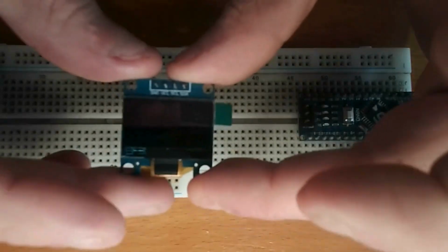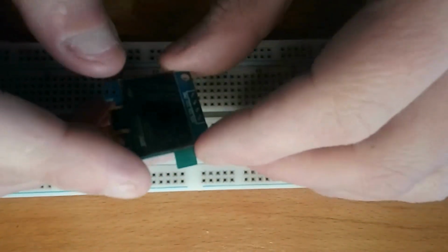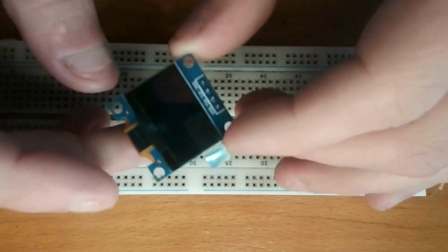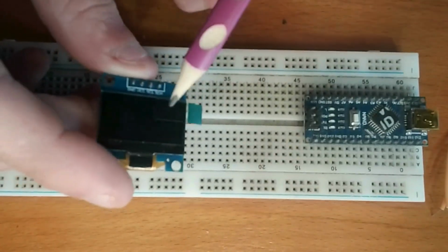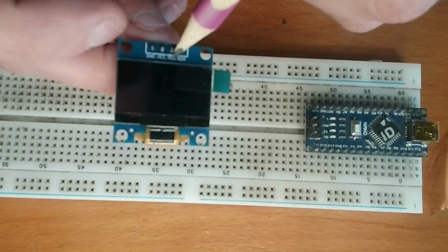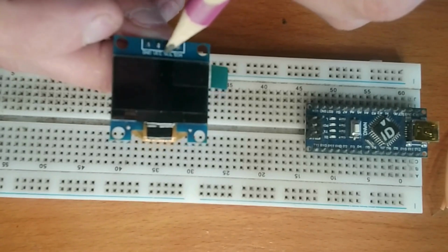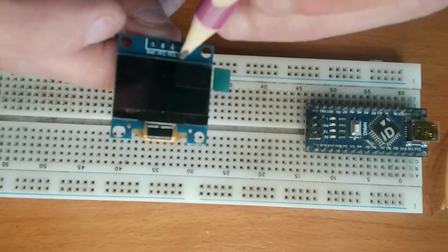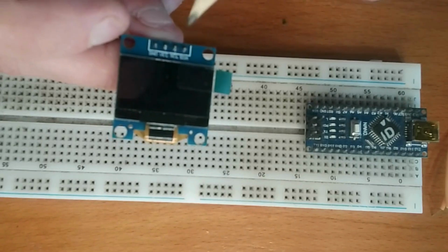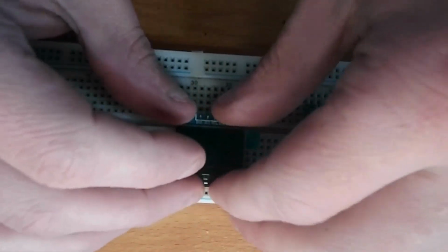Okay, so now I'm going to go ahead and connect up the OLED display right here. And this is an I2C OLED display. And you'll be able to tell if this is an I2C OLED display because the second last pin would be SCL, and the last pin would be SDA. If those pins match, then this is an I2C display. So we can go ahead and just put this onto the breadboard. So we're just going to fit that right in there.